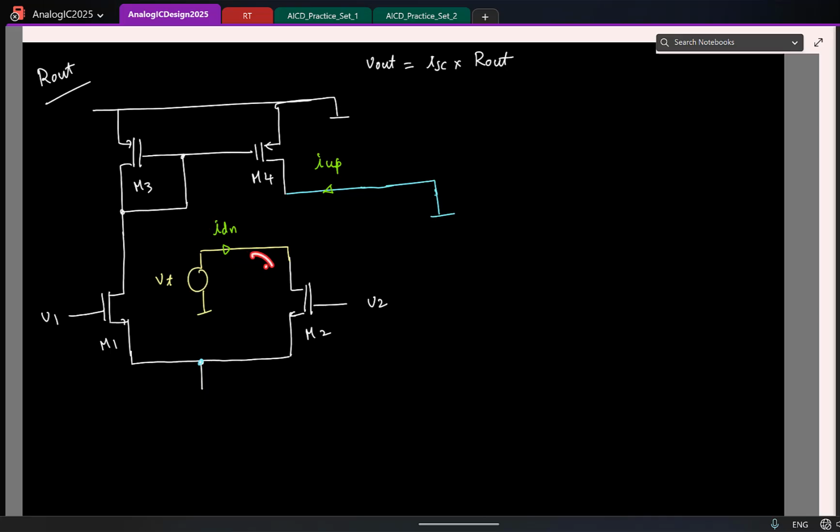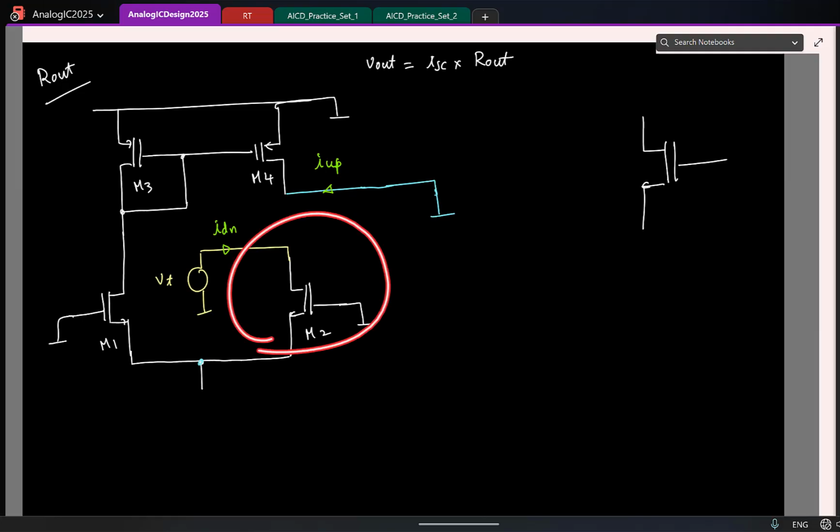I'm finding the effective resistance looking here. Fine. So if I were to draw that part alone looking down, again when I'm computing the test voltage test current business, what will I do to the inputs? Yeah, because I don't want them to contribute to my test current, so I'll actually have to short them. Right. So I'll try to draw the effective setup that I have here.